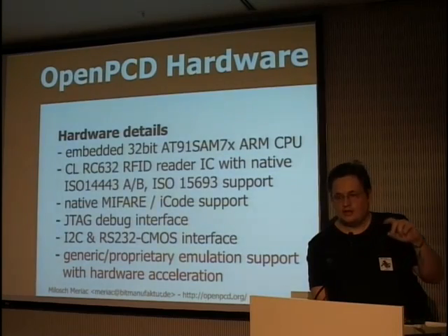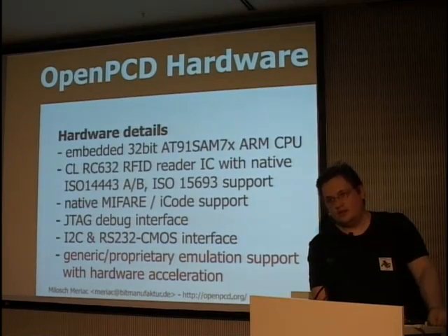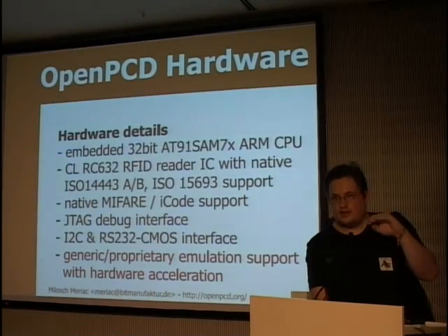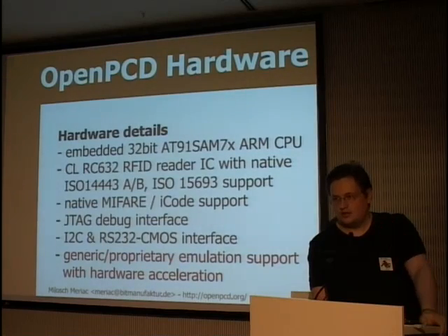And then we put this frequency again on the output pin, which is fed back into the reader IC again, and works as a clock for the DMA interface. So this means that whatever protocols you decide to use, you can time them very exactly to the reader frequency, the 13.56 megahertz.